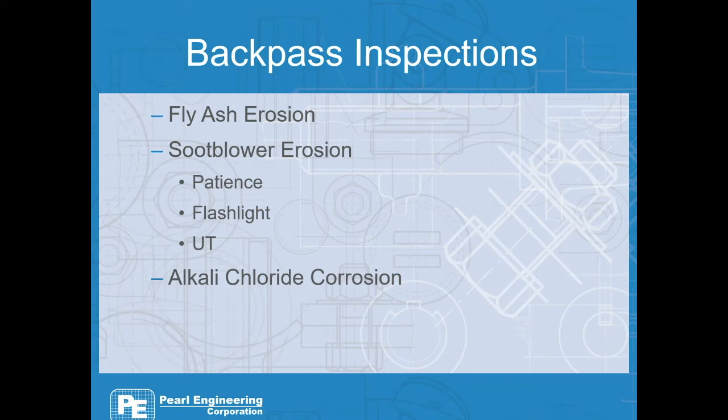Subfloor steam typically will ricochet off the hanger tube and start to cut right at that interface. Everybody's got a different interface, every boiler manufacturer, whether it's a scallop or some sort of handcuffs, and they're all prone to accelerate that subfloor erosion.